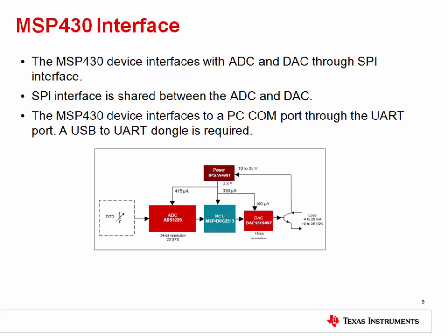For the processor selection for this TI design, the value line MSP430 device was selected for overall low-cost design. The 16K flash option was selected to meet interface and power requirements for the processor. Another option to consider for an RTD sensing solution would be the MSP430 i20XX that have 4 built-in 24-bit sigma delta converters.